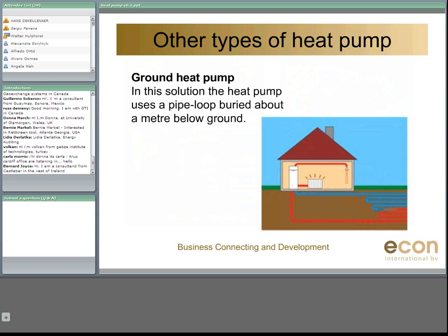The house should be, of course, located next to a lake with wide access of water. The place of the collector must be free of activities. So if someone is going fishing over there, you might have some problems. Also take care of ship movements, etc. The collector must be deep enough in case you have freezing problems.